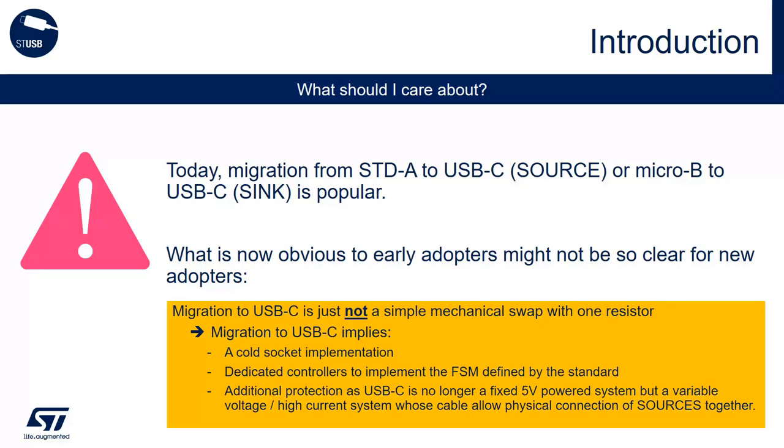So we need to consider protecting by default every USB-C port to 20-volt shorts or more, even if the application is only for 5-volt, since not only 5-volt can be available, since voltage is scalable.